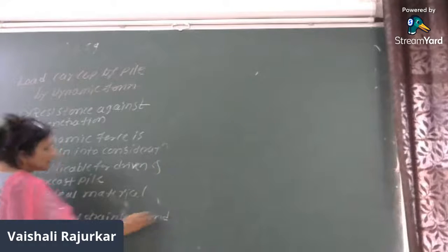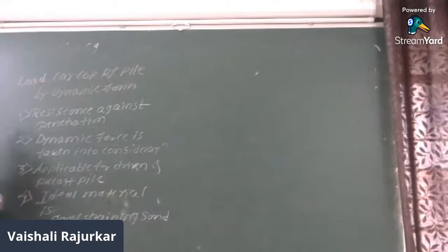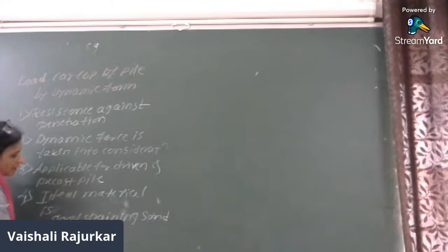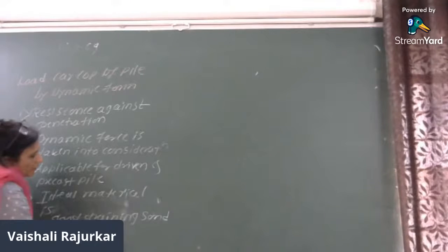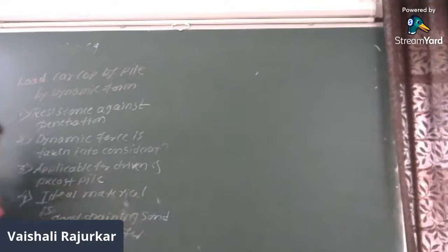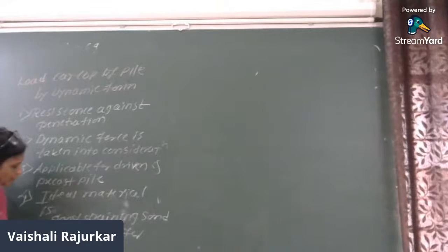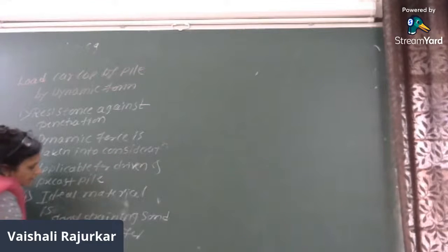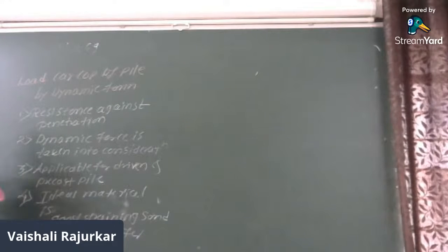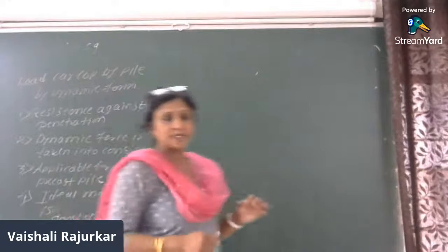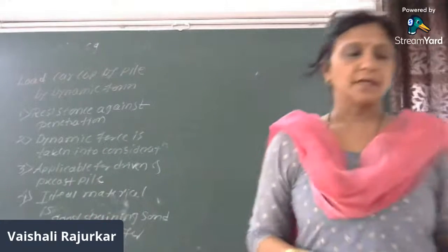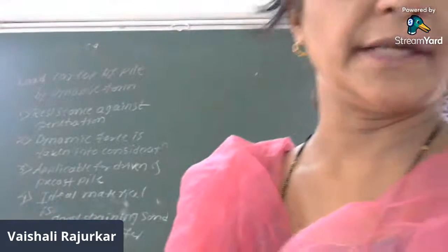And where will it not be suitable? Not suitable for saturated clay. It is not suitable for saturated clay where there is an existence of pore water pressure. So these are some of the features of the test.